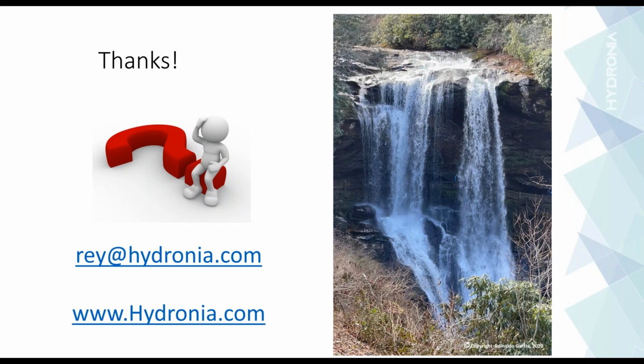And in doing so, your dams will fail not simultaneously, but according to the times that you select in your dam breach models. In the dam breach component, you select the time at which the dam breach component will start. That doesn't mean that the erosion will suddenly occur, but it will start eroding the dam at the time that you select. So yes, the answer would be yes in that case.